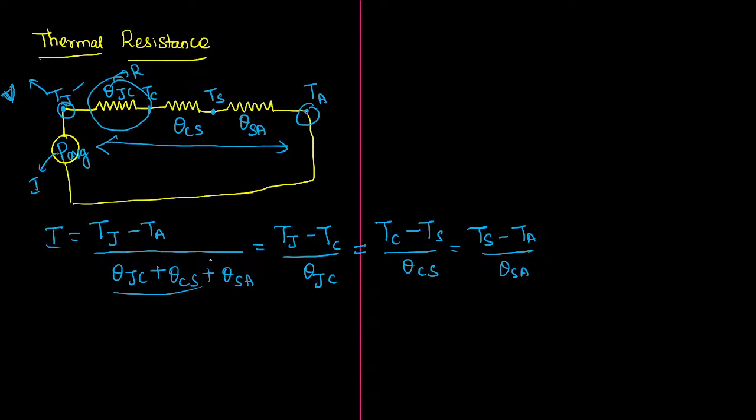Okay, so this is how we are estimating the value, and this is basically called P average, the total heat generated. It will be a step by step process. There they would have inserted the sink, and after that it will be dissipated through the atmosphere. First, heat is generated at the junction, then that heat will be transferred to the case. From the case we are transferring this temperature to the sink. From the sink it will be dissipated through the atmosphere.